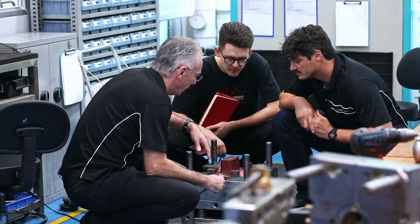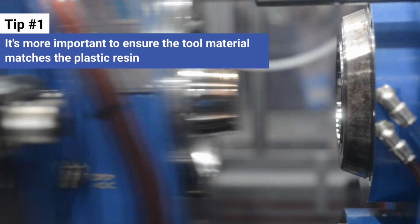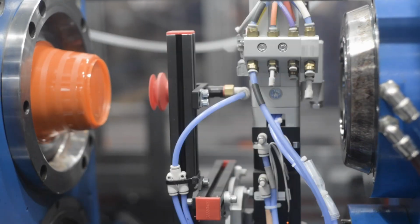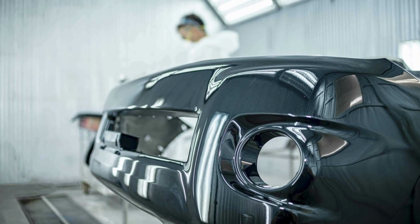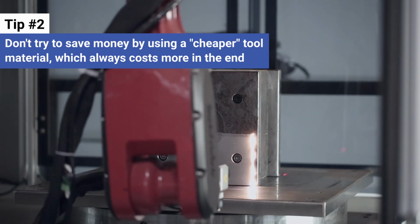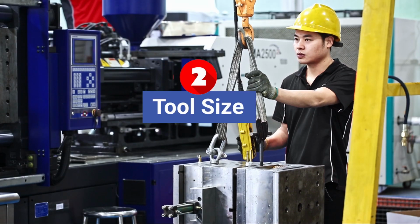Instead, from a product developer's point of view, it's more important to ensure the tool material matches the plastic resin, since some resins can attack certain tool steels, especially if abrasive fillers like glass fibers are used. Our advice is not to try to save money by using a cheaper tool material, which always costs more in the end. Number two, tool size.